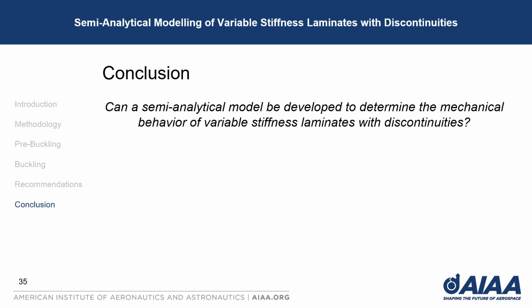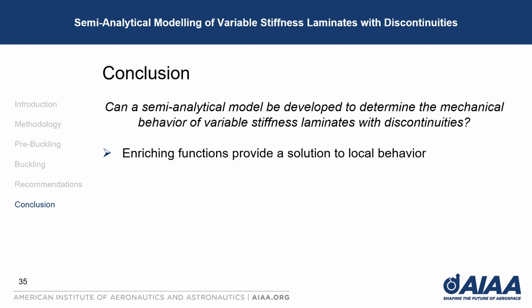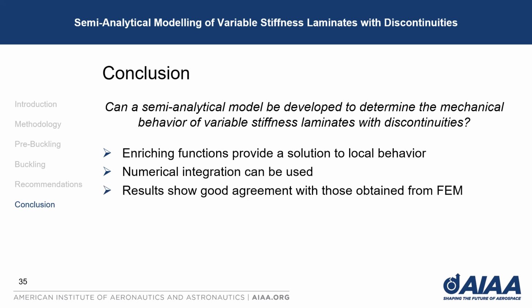So in conclusion, can a semi-analytical model be developed? Well, enriching functions provide a solution for local behavior, and numerical integration schemes can be used to make life a lot easier. Results show good agreement with results from finite element methods, and the model is easy to use with varying inputs, for instance with stiffness variations, fiber paths, etc. So yes, such a model can be developed.